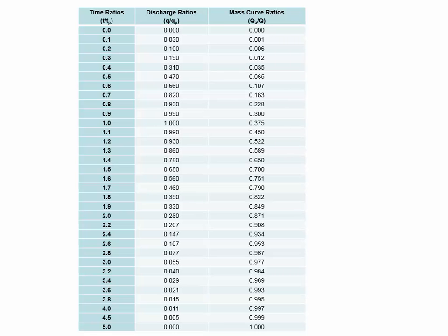What we can do to calculate it is just multiply. Q at 87 minutes is 0.28 times Q sub P. So that's 0.28 times 1992 CFS per inch of rainfall excess, and that's 558 CFS per inch of rainfall excess.